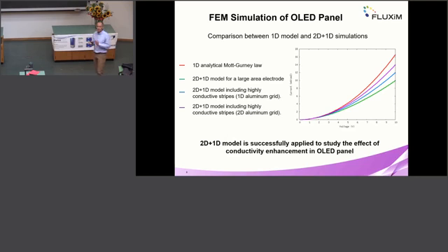To reach a certain current density, we have to apply more voltage, and that's because the series resistance in this transparent ITO adds a voltage drop from the center to the boundary of the OLED, and this voltage drop we have to apply in order to get the same current. So we're shifting away from the ideal JV curve because the electrode is limited.